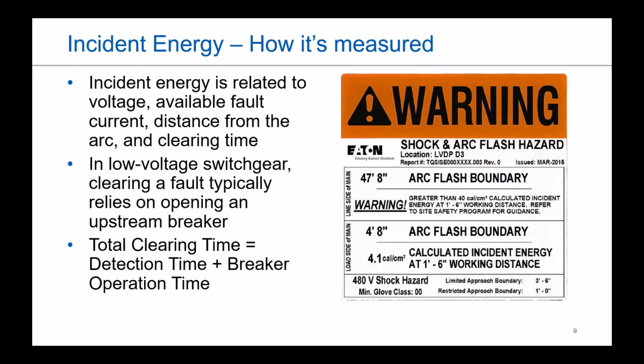But incident energy itself, there's a number of factors that go into it. If you're ever curious, you can always try to find yourself a calculator that's to the IEEE 1584 standard. That'll give you the ability to go through and see, okay, what are all the different parameters that go into place to give me my estimations for what the incident energy level is.